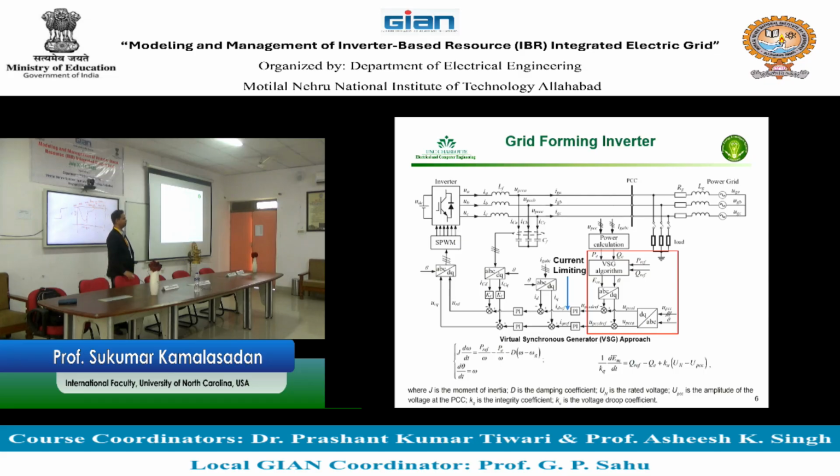This is how the frequency wobbles in general in an interconnected system with many generators working. So here each generator's governor with droop will act. Okay? So this is what we generally call inertial response. And this we call primary frequency response. This is called secondary.